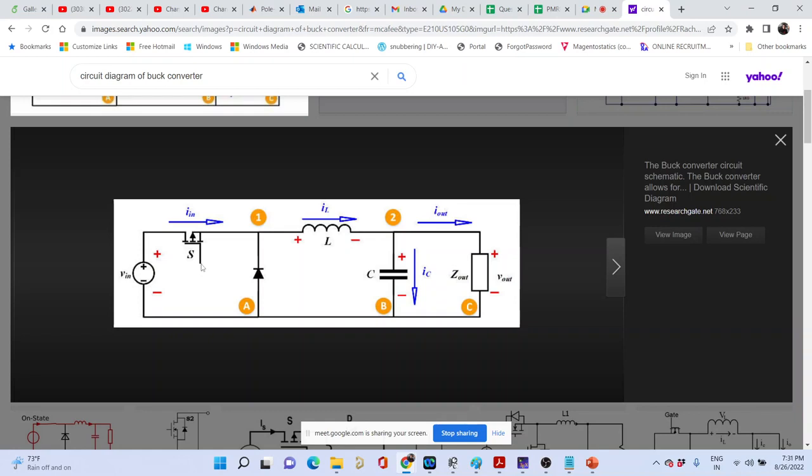I am saying plus 10 volt. But with respect to whom do I need to provide this 10 volt? Anybody? With respect to whom are you giving this gate pulse? Sir, maybe grounding or 0 volt potential. No, you are giving this with respect to the source terminal. You have to have a 10 volt with respect to the source terminal, right?